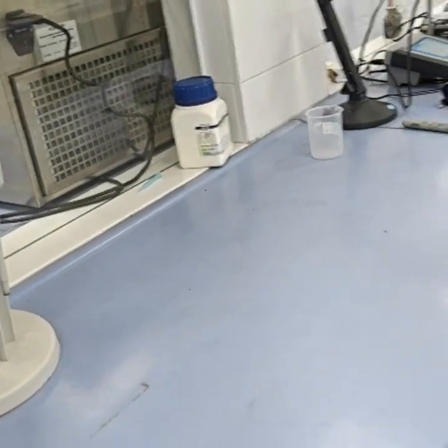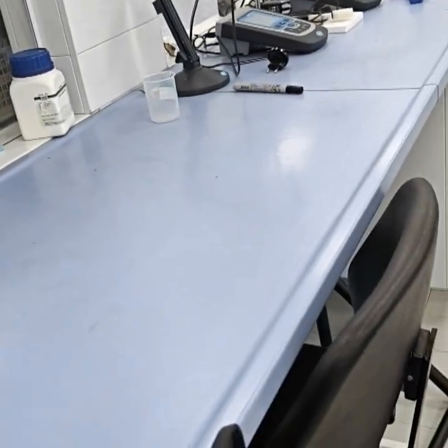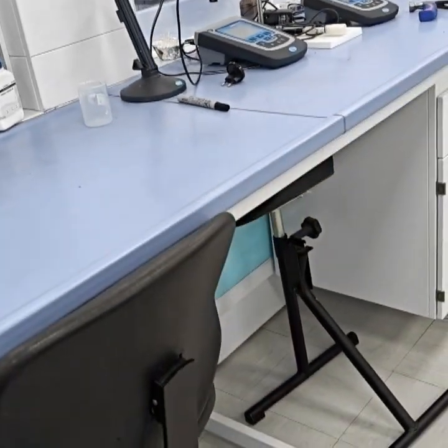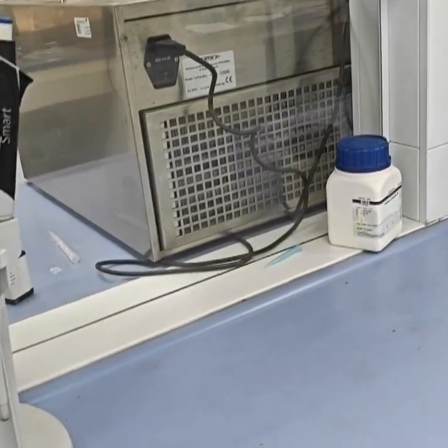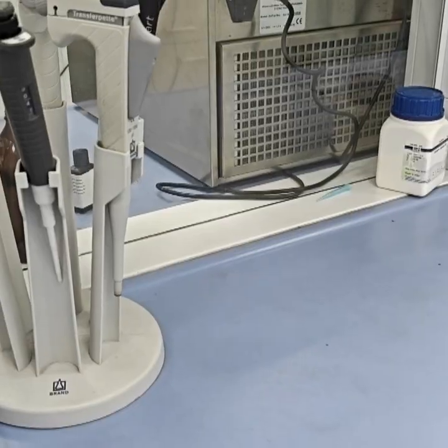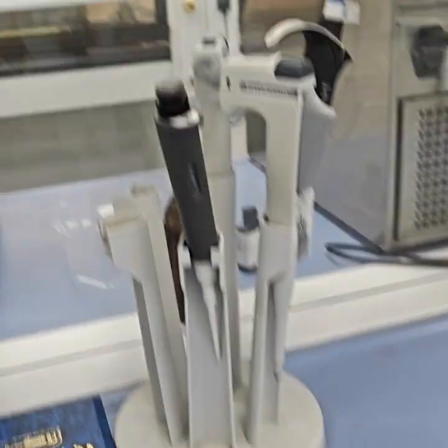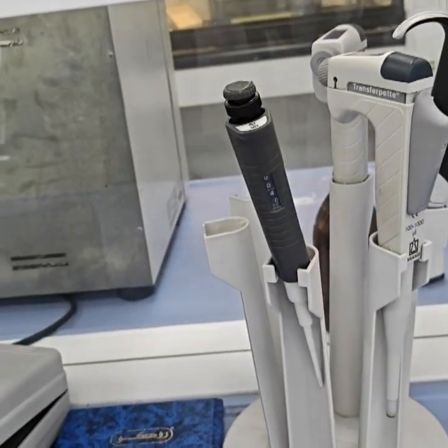Now, there are some of the tests that we usually do in the laboratory. For example, if you want to find the pH of the water, it should be analyzed immediately, and the holding time of the sample should not be more than 15 minutes. If you are analyzing BOD of the water, you must cool it to 4 degrees C, and you cannot add any chemical preservative, and the holding time could be 8 hours so that the